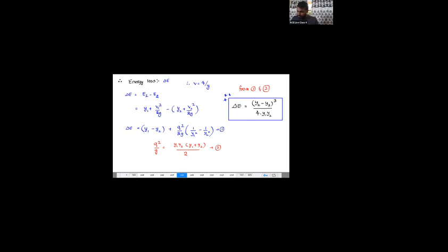Now, let's come to the next section. Once we know the energy loss, we can find out the power loss during a jump. That power loss is equal to gamma W into the discharge Q into delta E. So the power loss is nothing but gamma W into Q into delta E.